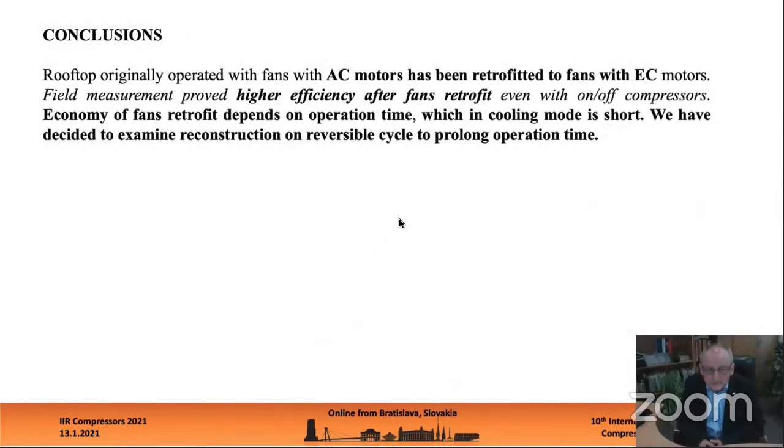Conclusions. The rooftop originally operated with fans with AC motors has been retrofitted to fans with EC motors. Field measurement proved higher efficiency after the fans retrofit, even with on-off compressors. Economy of the fan retrofit depends on operation time, which in cooling mode is short.